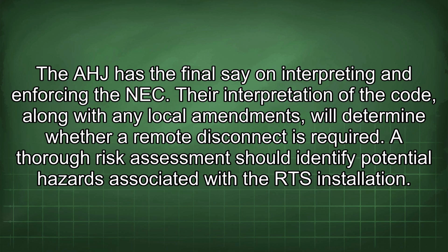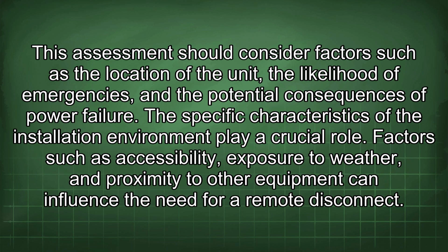A thorough risk assessment should identify potential hazards associated with the RTS installation. This assessment should consider factors such as the location of the unit, the likelihood of emergencies, and the potential consequences of power failure. Specific characteristics of the installation environment play a crucial role. Factors such as accessibility, exposure to weather, and proximity to other equipment can influence the need for a remote disconnect.